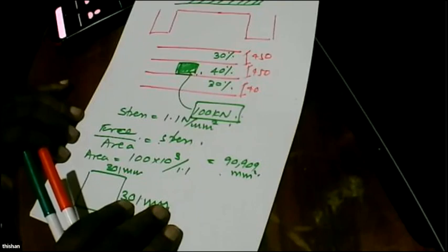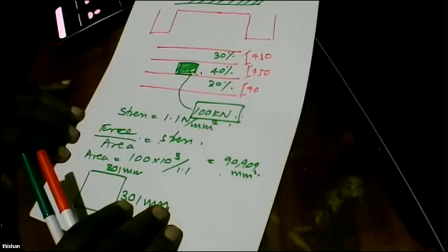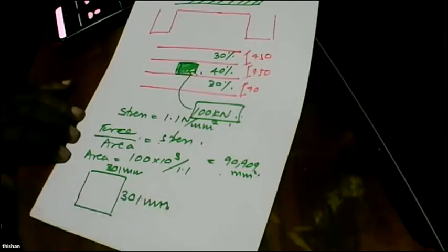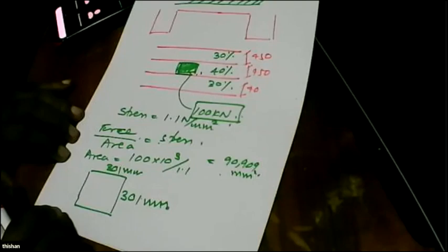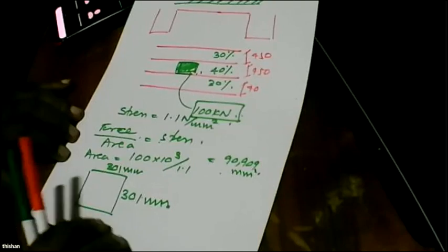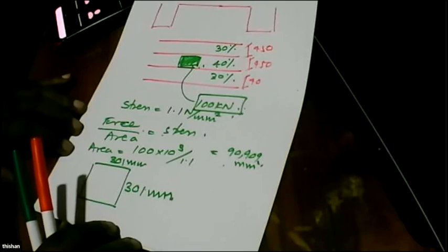In addition to that, you have to make sure if there's a very heavy wheel load of 100 kilonewtons acting on a slab, that is 10 tons, then that load could be taken by the panels, or the reinforcement in the deck is sufficient to ensure that this type of heavy load will not cause the failure of the bridge, right?